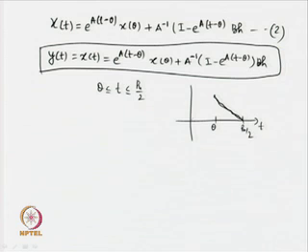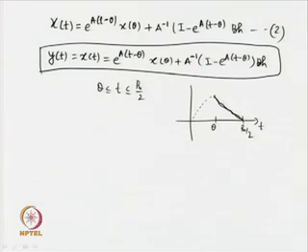So, the earlier one we have obtained is like this. So, finally, it is possible to obtain the positive half output of the sustained oscillatory output of a system under relay control in this form. This is the plot for y(t), and again I would like to mention that the dotted part of the output is obtained with the help of positive input h, whereas the solid part of the output is obtained with the input to the system remaining minus h. So, input to the system is minus h.